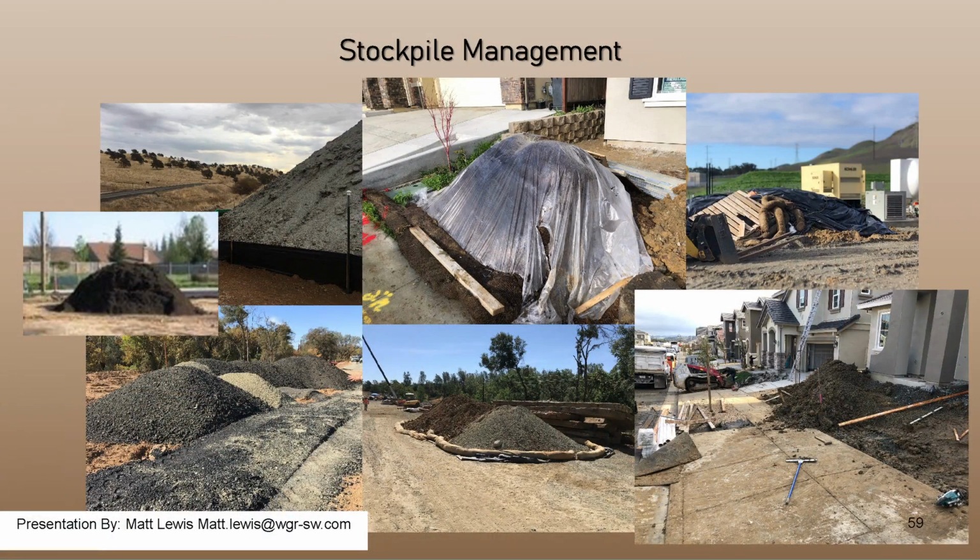And then that lower one is usually the type of stockpile that you will get, gravel stockpiles, you'll get a lot of wind erosion. And so those are the ones that you'll tend to want to get covered, especially during the summer. They're just going to be whipping up all kinds of wind erosion. All right, we're getting there.